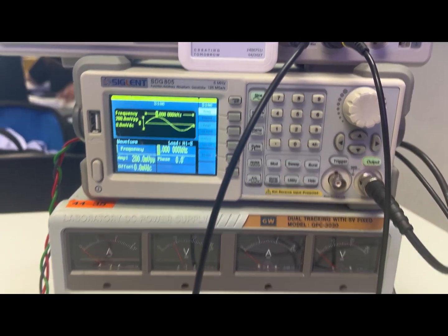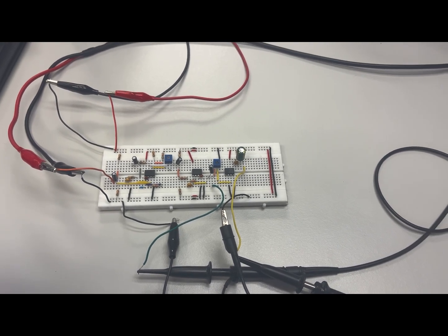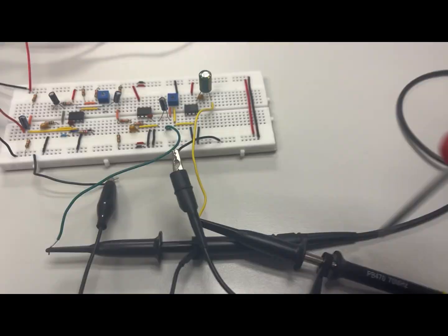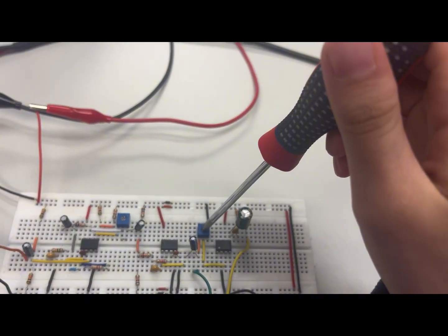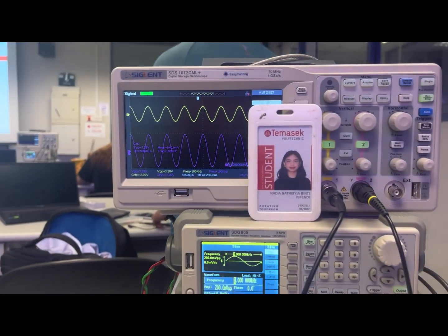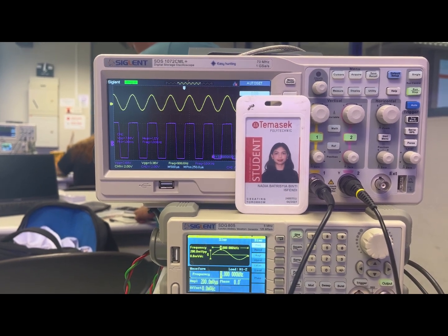At 1 kHz, keep TP4 at channel 1 and place channel 2's probe at TP5. The output voltage is around 7.04 volts. By adjusting the trimmer P2, we can control the output at TP5. The final output will then be the maximum sine wave attained without being saturated.